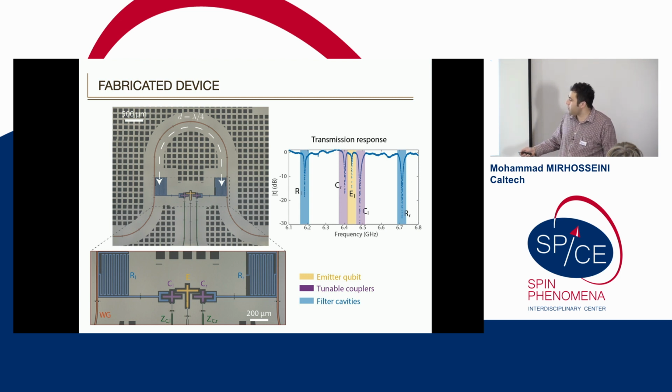This center qubit is our emitter. These coupler elements are also, if you think about their hardware, actually qubits. These are all transmon qubits. So we have the emitter, we have this coupler element on the right and left. These on-chip ports apply these periodic fluxes. And then we have some planar resonators, which are the resonators described before. And they are coupled to a waveguide at two different points, separated by lambda over 4. In this case, lambda over 4 is about 4 millimeters.